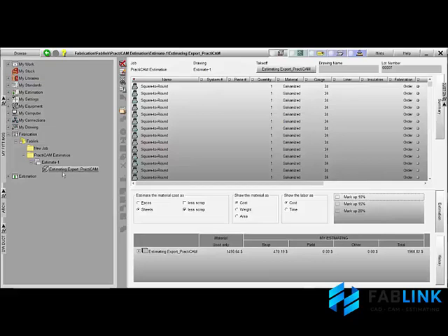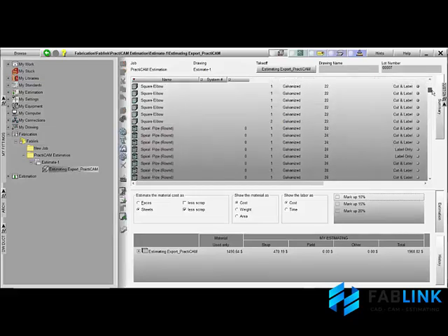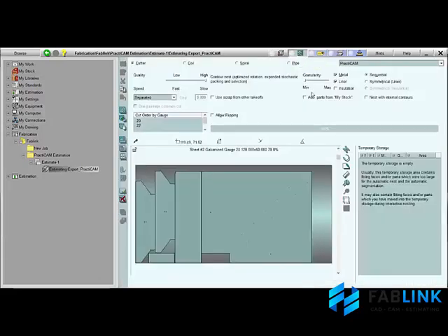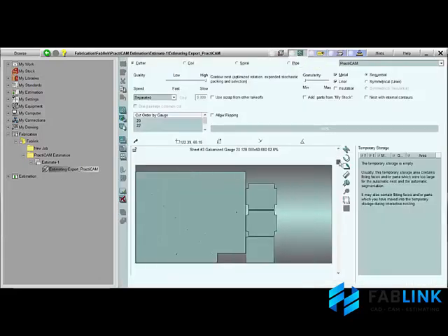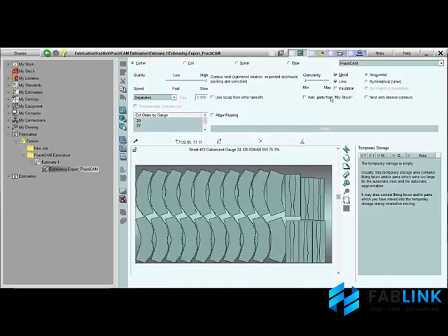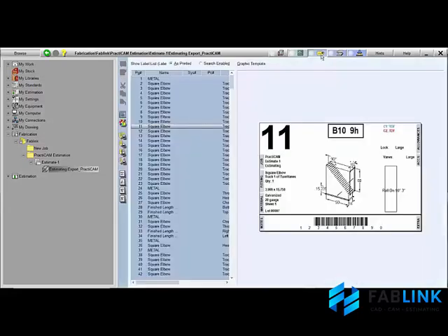Here you can see as we highlight a drawing and download it direct to PractiCAM. Looking through the takeoff we downloaded, we can see exactly what needs to be ordered and what needs to be fabricated. Everything that is being manufactured is already nested and ready to cut. And don't forget that because PractiCAM is a manufacturing system that does nesting, it knows exactly how much metal you're using for fittings you make or in the scrap.